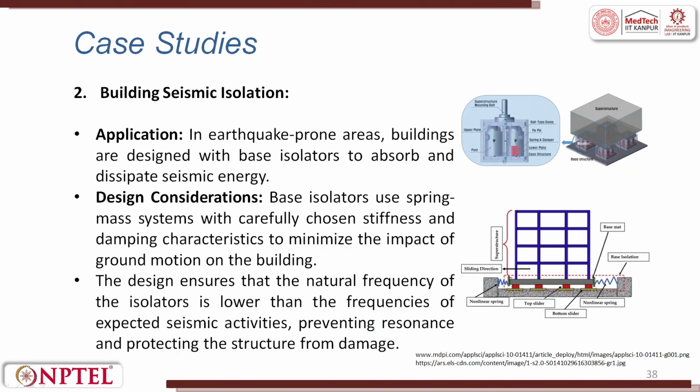When we talk about buildings, seismic isolation, you can see this is the superstructure of a building, and here they try to keep some dampers at the base. It can be a pad or even rollers, which roll and then dissipate energy. In earthquake prone areas, buildings are designed with a base isolator to absorb and dissipate seismic energy.